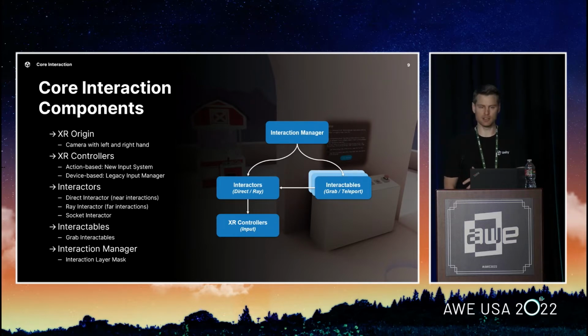As Dorrene stated, we support both the legacy input manager and the new input system package. As you can see, the action-based controllers are plumbed through the new input system. The device-based are plumbed through the legacy input manager. But keep in mind that if you plan to use OpenXR, these are currently only supported through our new input system package with the actions. Despite which model you end up using, the functionality remains the same, and the controller creates an abstraction layer on top of the specific devices, allowing you to use a more simplified input action such as select, activate, move, pressing on the UI, things like that.